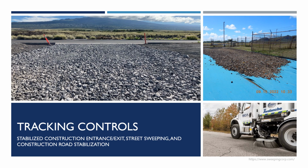Tracking controls include stabilized construction entrances and exits, street sweeping, and construction road stabilization. These BMPs minimize sediment tracking outside of the project limits. Stabilized construction entrances and exits are required when project vehicles and equipment travel from a disturbed area to paved area. This transition causes sediment trackout, resulting in tracks of sediment on the paved area that has the potential to get washed into the storm drainage system during a rain event.